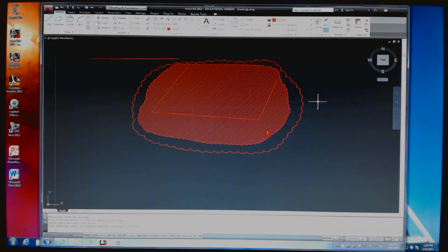When you start getting a lot of blocks on the drawing and you try to hatch, a lot of times the hatch doesn't want to read the block for some reason, so it hatches right over your block. So we'll sometimes have to use the wipeout on our block to get the hatch out of it, okay? And I'm going to show you something I'm talking about.